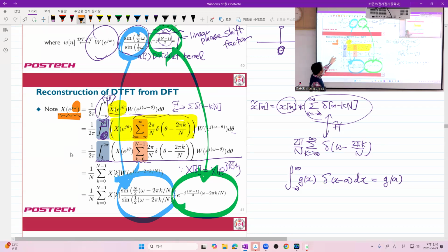If our signal was time limited, we can get the DTFT exactly, as finely as we want. Because this is a function of omega, and omega ranges from minus infinity to plus infinity, even though it's periodic, right? So if we want higher and higher resolution, just evaluate this Dirichlet kernel at as many points as we want. Got it?